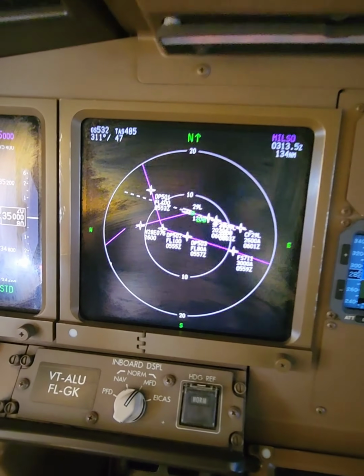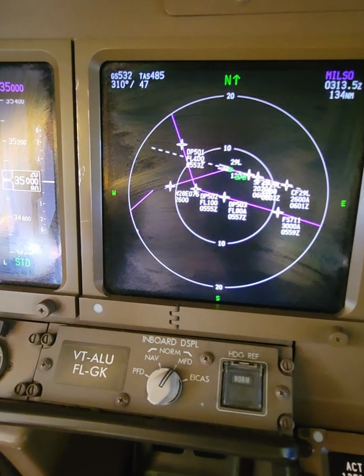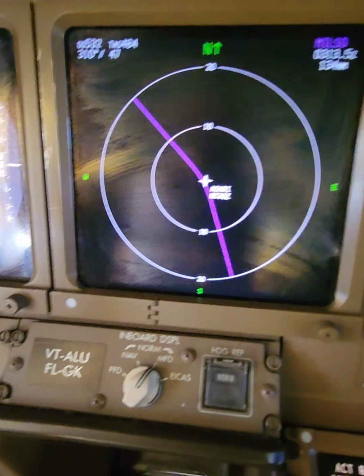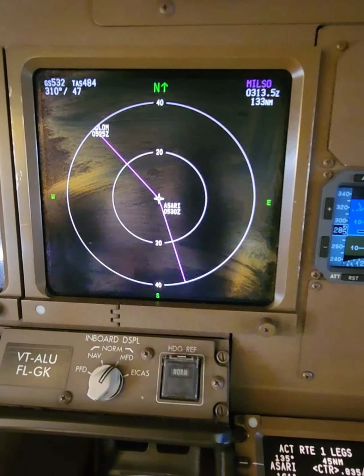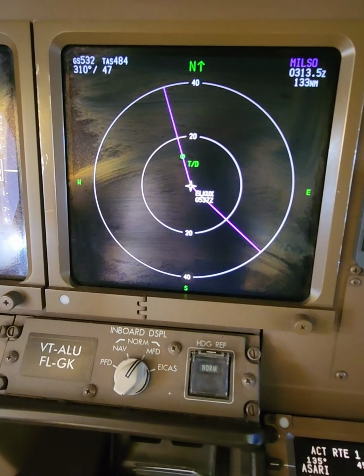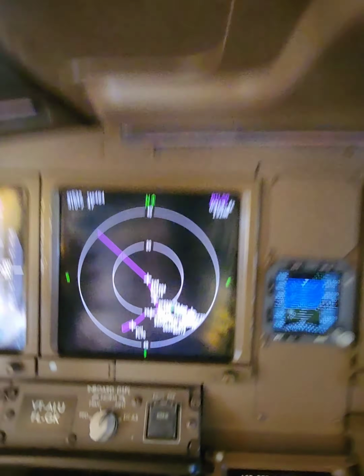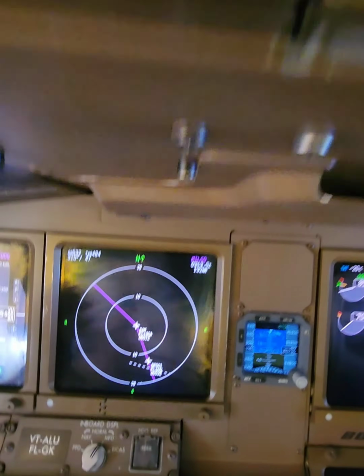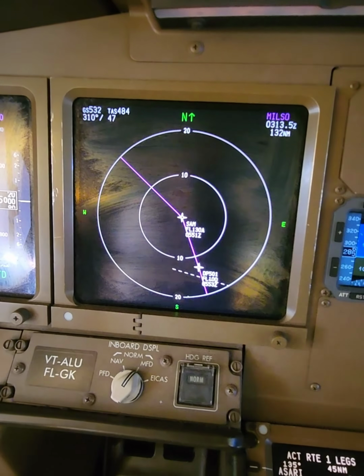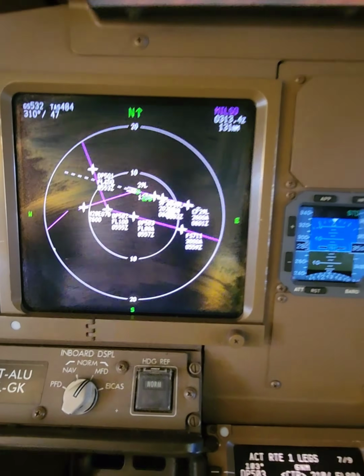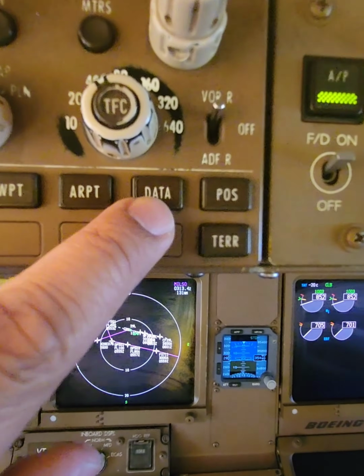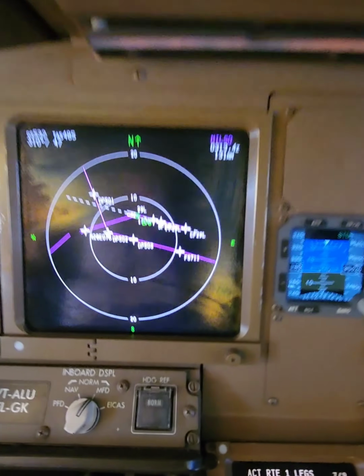You can see approaching from the northwest, going southbound, crossing the extended center line of the runway, which is a dashed white line, approximately 14.2 nautical miles long. Reducing the range to show it clearly. So that's the extended white line of the selected runway. So going down southbound, then downwind, and then the approach.